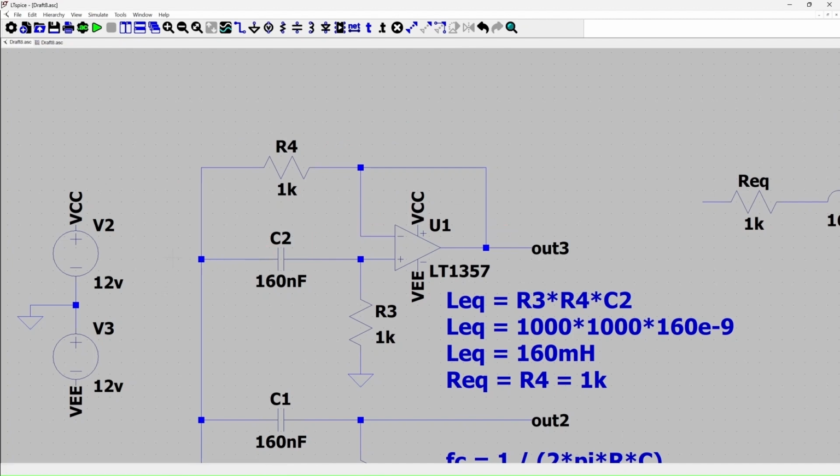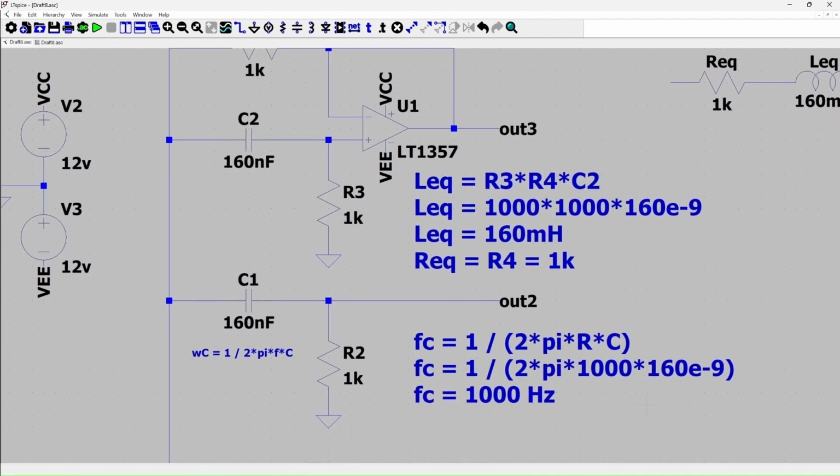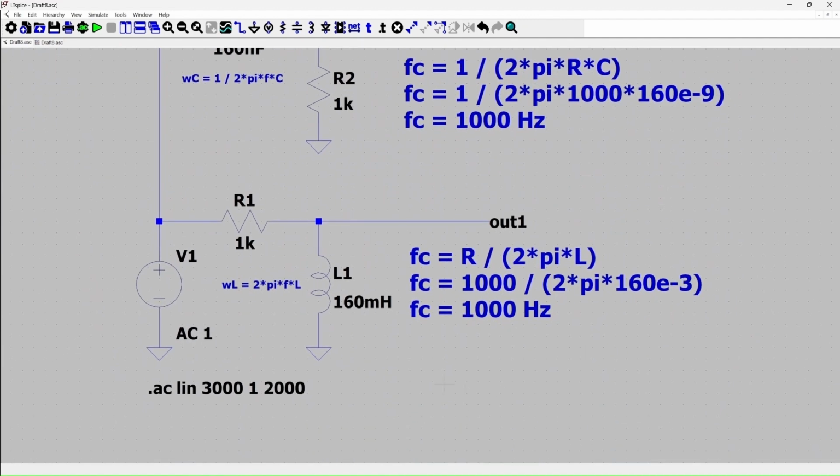Let's take the other case. When the frequencies are high, the capacitor passes them through, and the voltage drop appears across this particular resistor. Now, as per basic op-amp theory, this voltage must also get reflected at the input terminal. So this input is equal to whatever is coming from this side, and this forces the output to rise, which means the higher frequencies are being passed through the upper arm. And again, it is mimicking the RL circuit as shown earlier. For higher frequencies, this inductor acts like an open circuit. Since nothing can go to the ground, everything is passed on to the output.